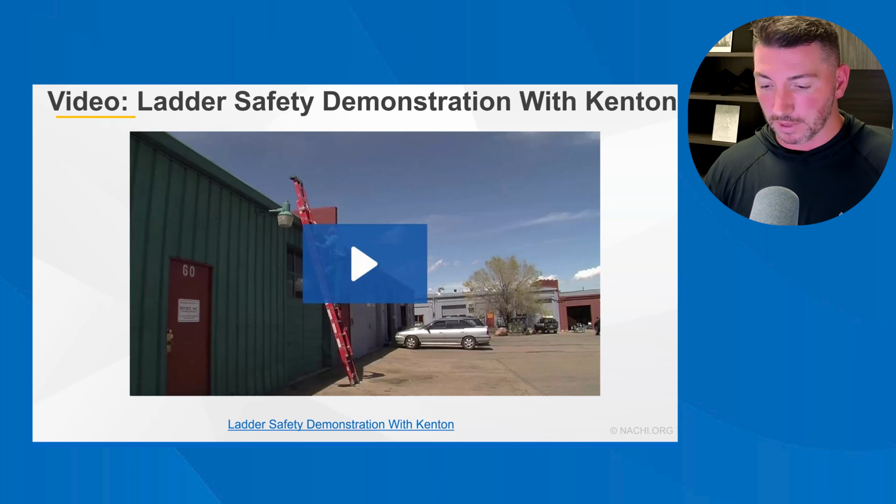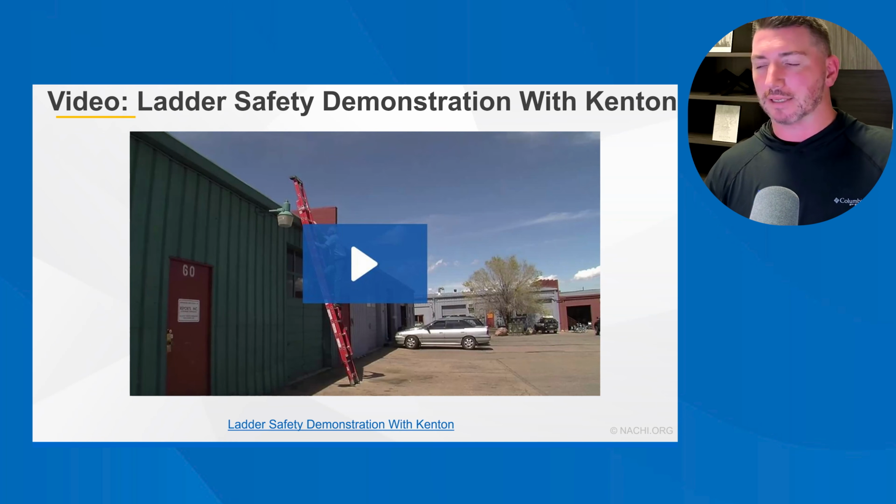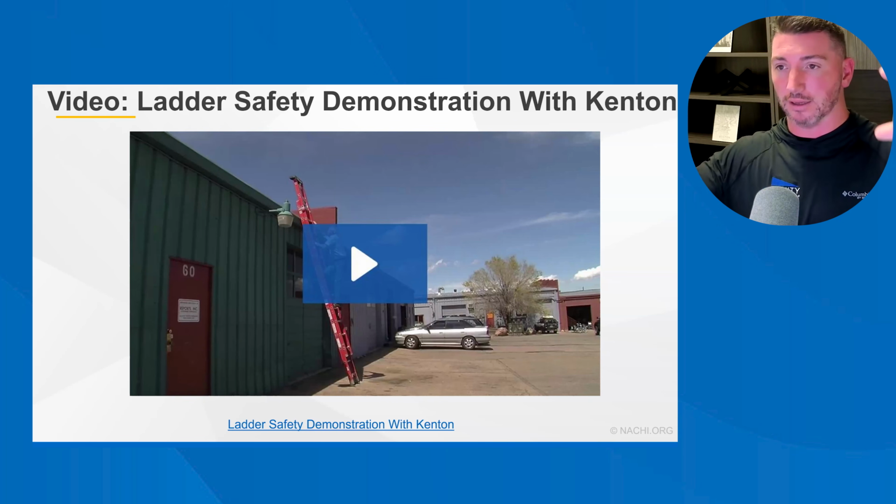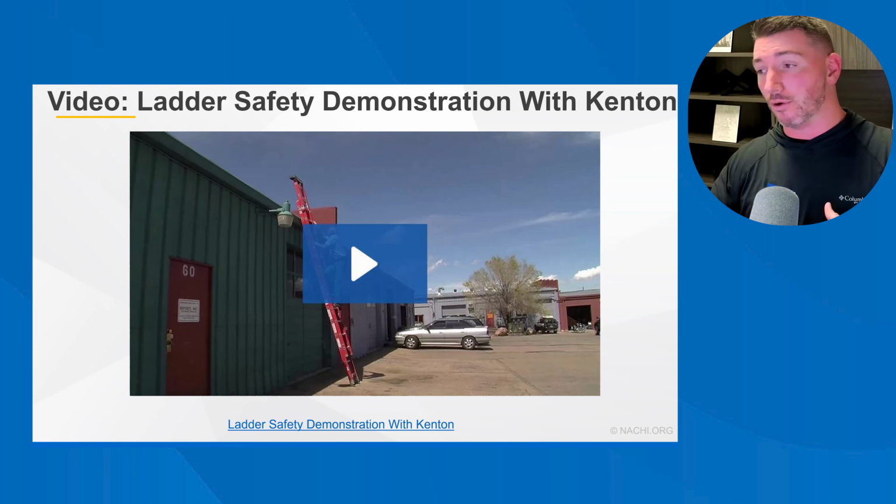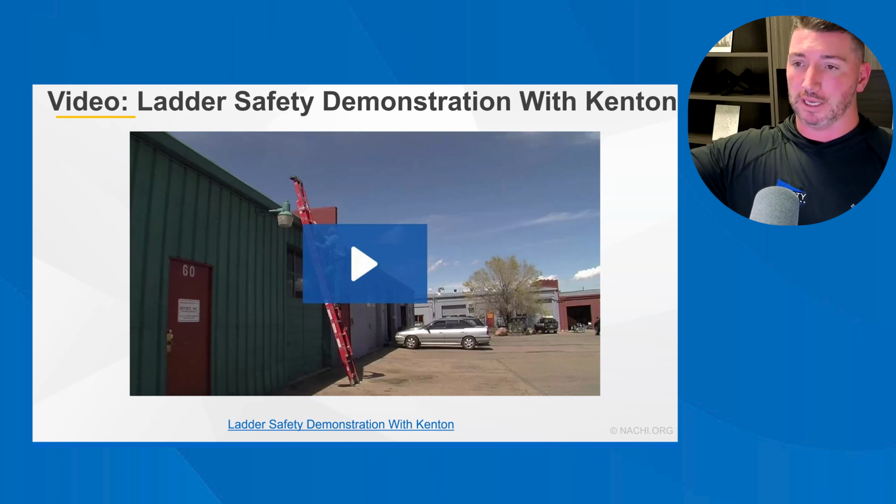Hopefully, we've all learned enough about what ladder safety is in this particular instance. And another thing I will say, just to circle back to that point, now Kenton's about to walk on a commercial roof, but in a residential application, one very hugely helpful thing where you don't need a gutter, and I forgot to mention this earlier, there's ladder standoffs, some are called bullhorns, and there's ones that are like an A shape, and they press into the side rungs of a ladder. Those require you to get the ladder a good bit over the eave in order to use,